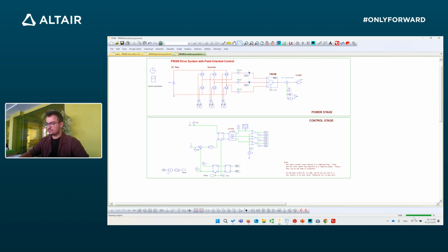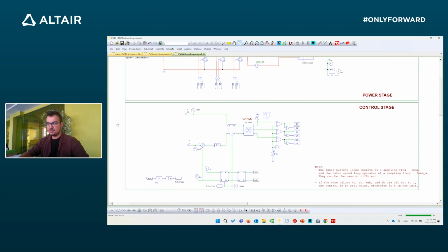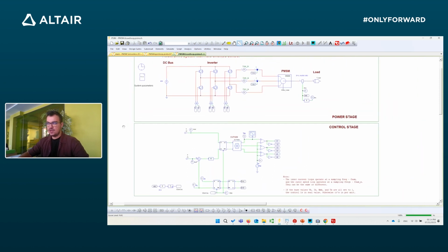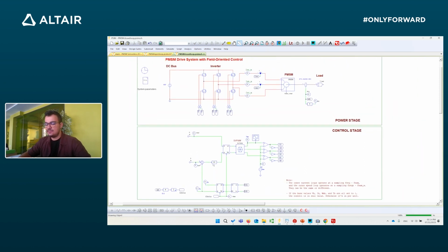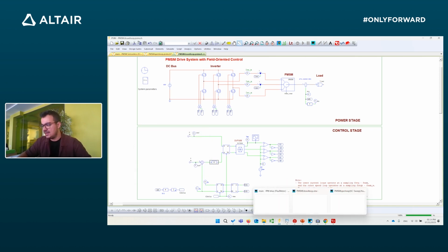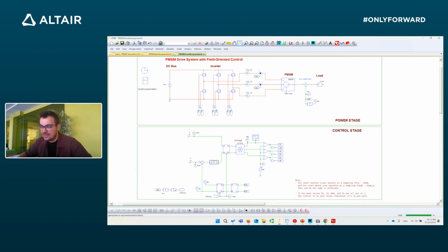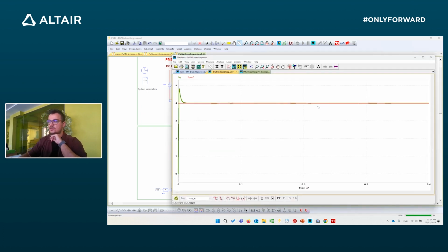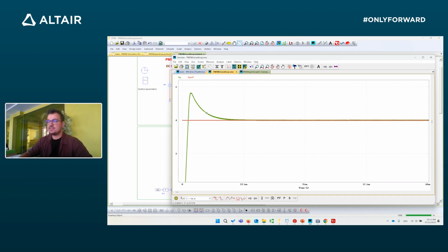Obviously, there is a PI controller block to use. Here it is. We have input the values here, close to the ones we selected now. We have the feedback for the IQ, and then we can run this. This simple simulation will be very fast, just 4 seconds to hit steady state. And here we see how IQ successfully follows the reference.